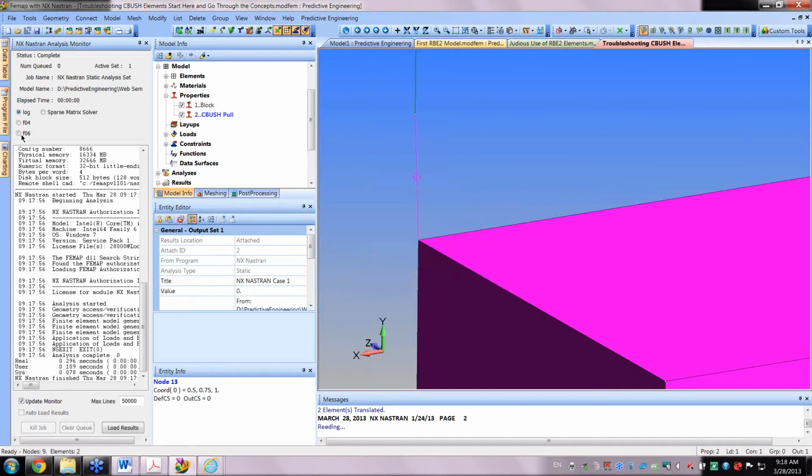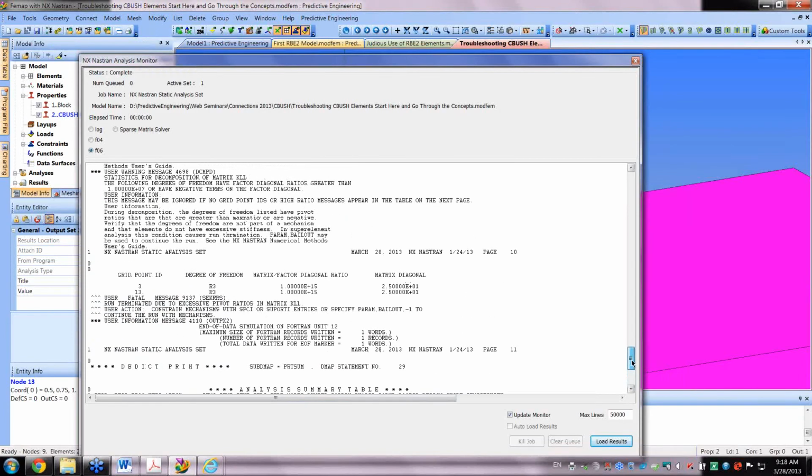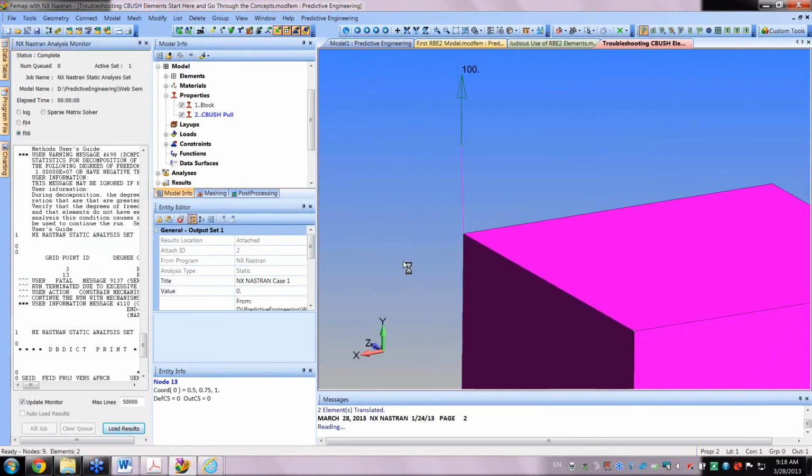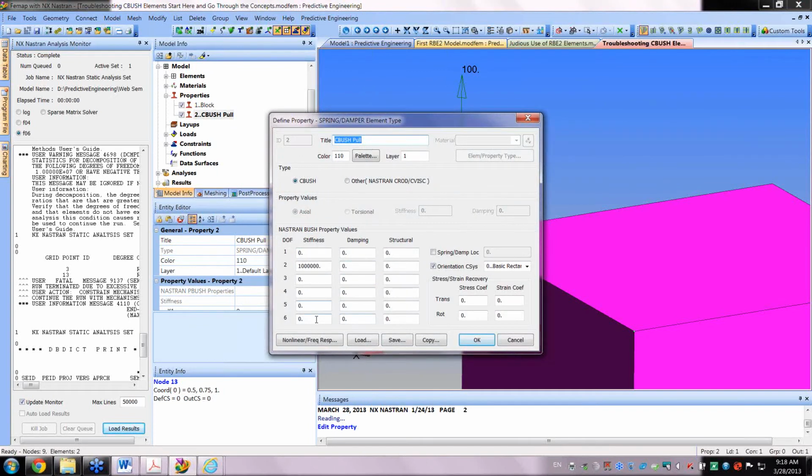failure, gone. F06, double click, expand the plane, degree of freedom, R3. Well, R3 is a Z. I moved it in X. So you guys are mechanically minded, you're going, well, of course, you moved it in X. You're going to create a moment around the Z axis. And we don't have any stiffness around the Z axis.